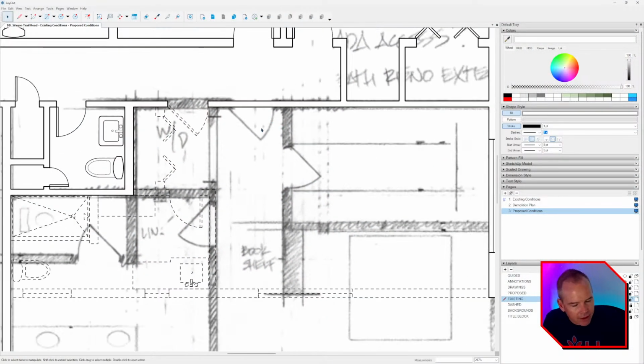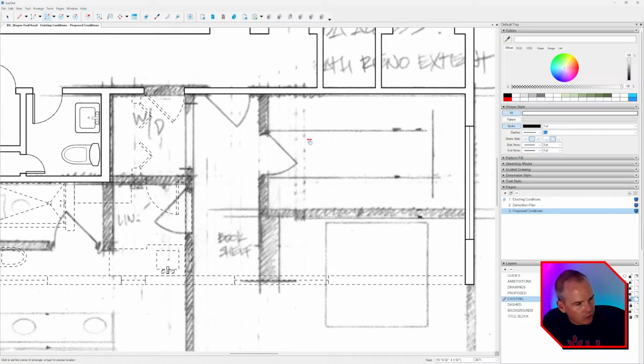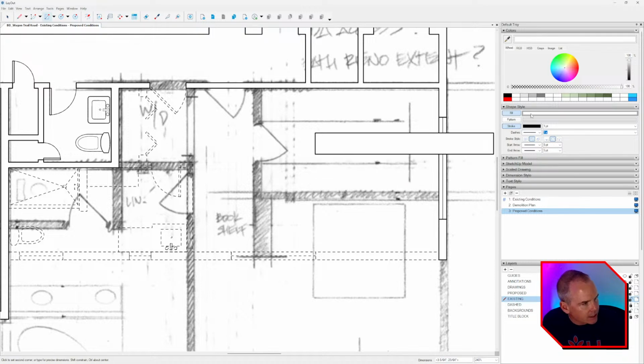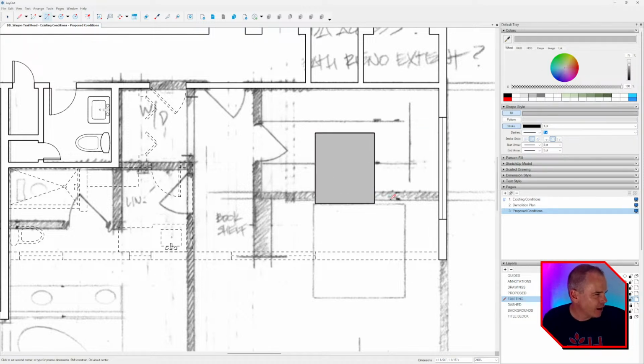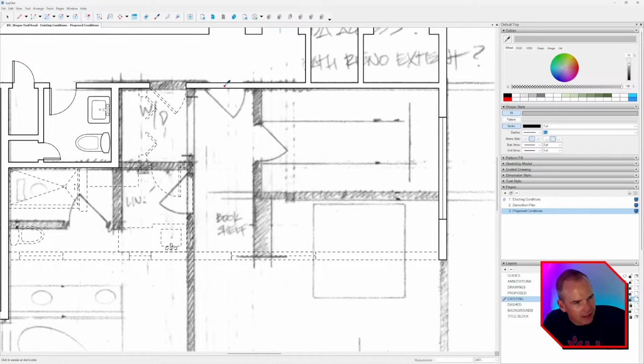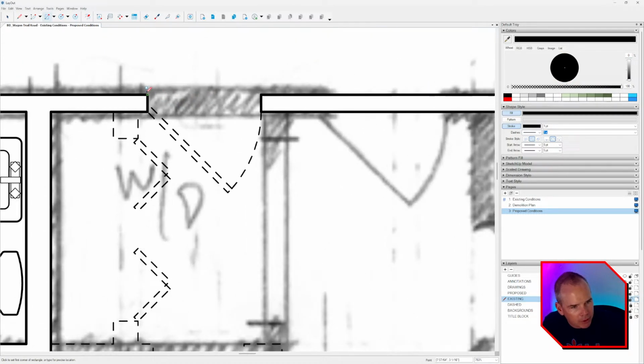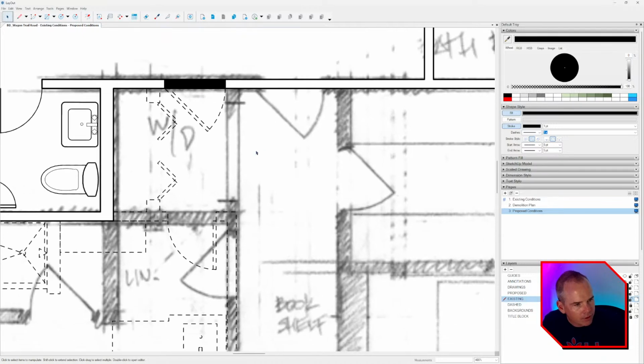So for me, if I tap the rectangle tool, and I now have, when I'm drawing a rectangle, settings in our shape style, and then the shape style like fill color is controlled in the colors dialog, and that's kind of it there. Okay, so you don't ever want to be messing around in there. You just want to activate your rectangle tool, tap S, and then sample. And then we're going to set our fill, which has that little black rim around it. We're going to set that to black. And we're going to build a new wall right here, like that.